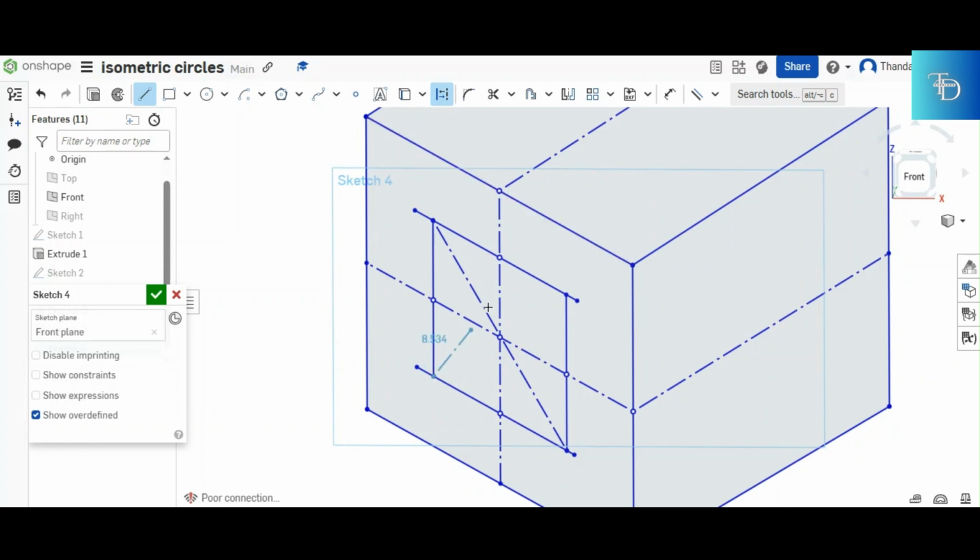So which means your line is going to start here to the opposite center, and then the second line starts from the very same point to the opposite center. Now this is the V that I'm talking about. You have completed the construction of the circle. The only thing that is left for you to analyze is the center point whereby you're going to place your compass, which is center point number 1 right there. We have a center point number 2 right there. We have a center point number 3 right there, and we have a center point number 4 right there.